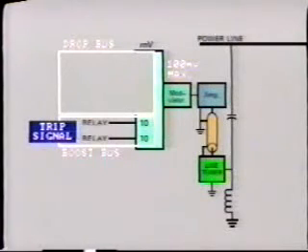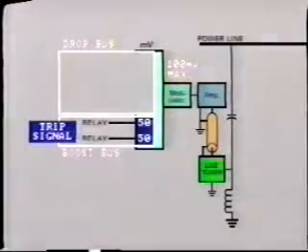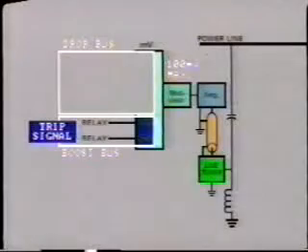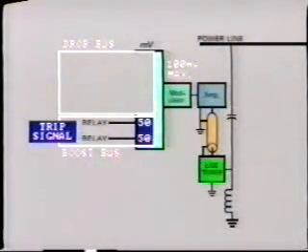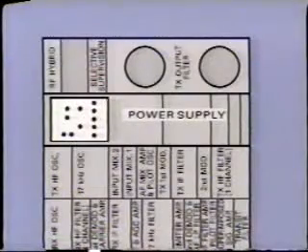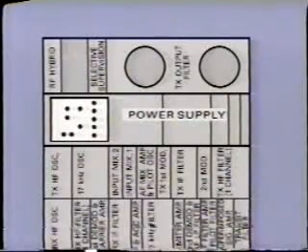At the same time, the boost bus modulation voltage is increased to 50 millivolts for each relay tone. We have now increased the important line relaying signals by a factor of 5 at a very small cost. Yearly inspection of these modulation levels is recommended. The potentiometers and amplifiers can drift, and the carrier could be over or under modulated as a result.